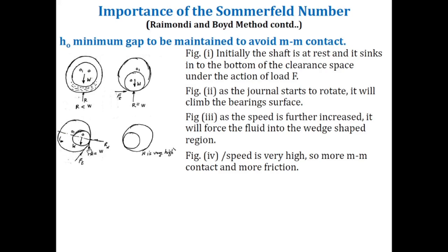is taking place. And as the speed goes on increasing, there is a tremendous increase in the heat in the bearings, and as you know, as the temperature increases, after some time your bearing may fail, and that is the reason why you should maintain some minimum gap here.